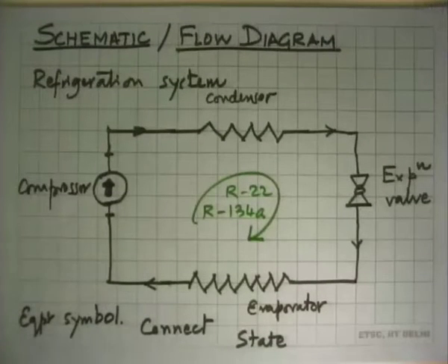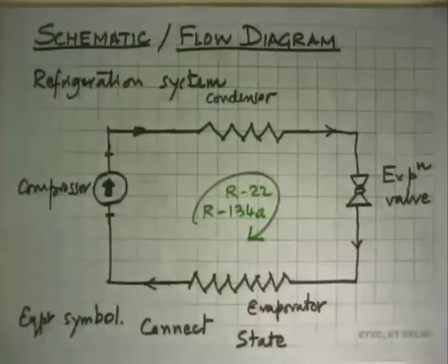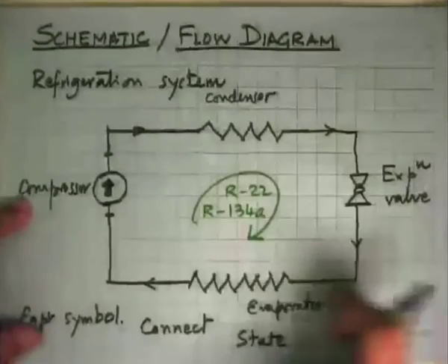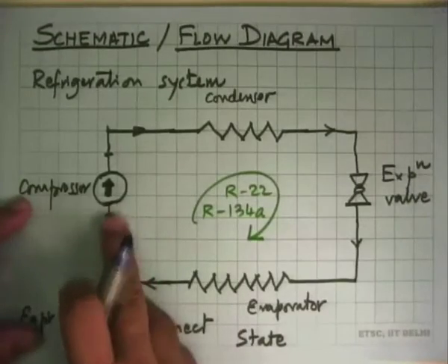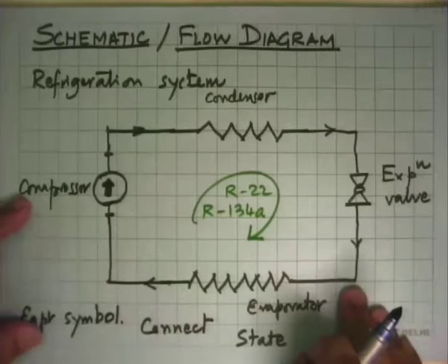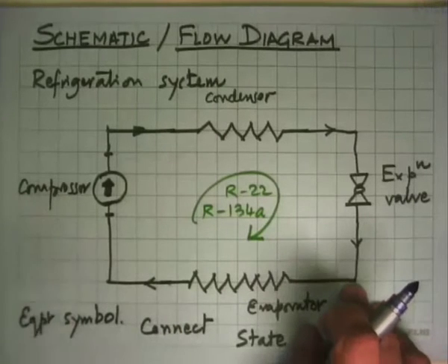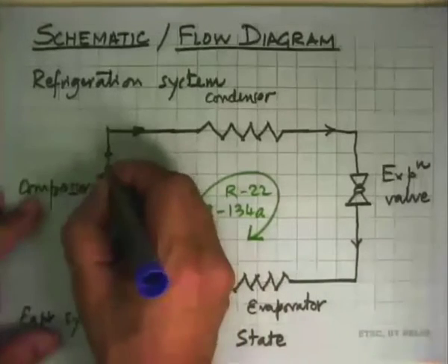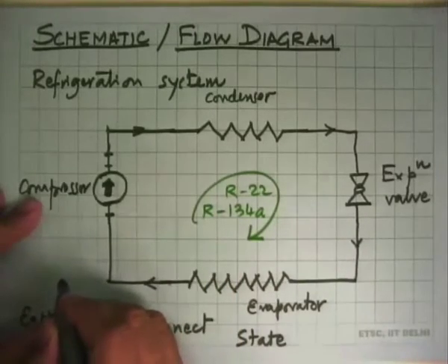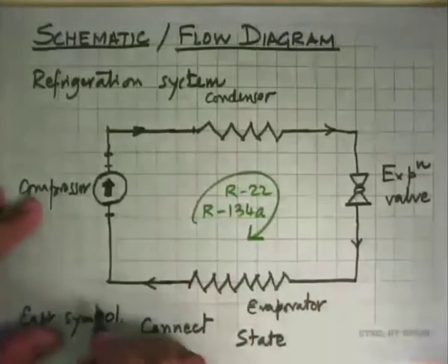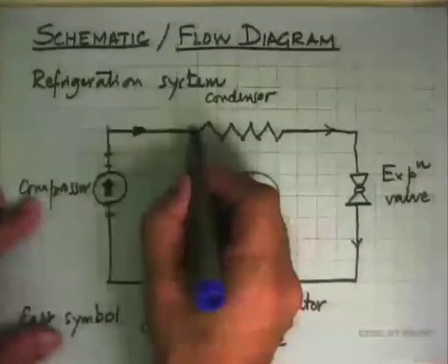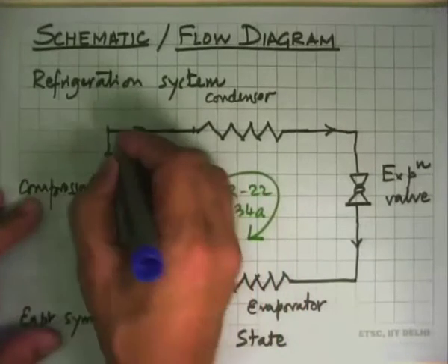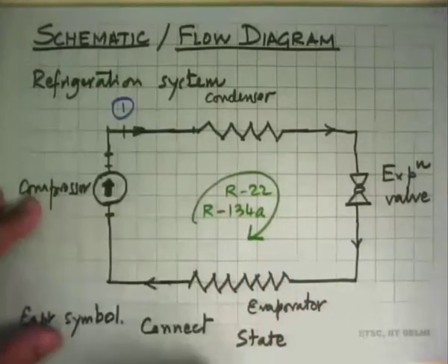So one of the things we do in the beginning here is that we say that in the pipes and the tubes, we assume that there is very little pressure drop or heat transfer. That means the state of the fluid coming out here is the same as the state going in there. So in this pipe, the state of the fluid is not changing. So we can say that this entire length, we can denote it by state 1.